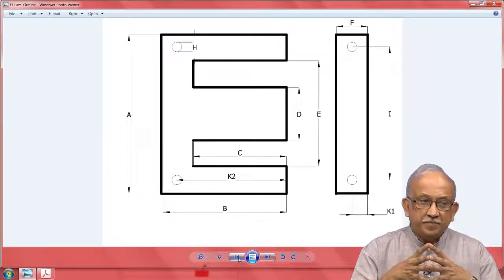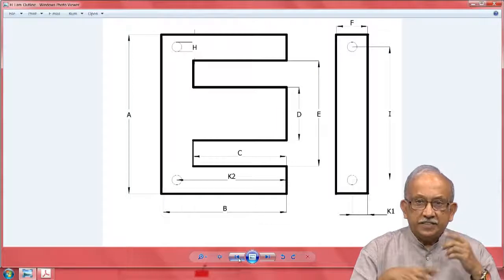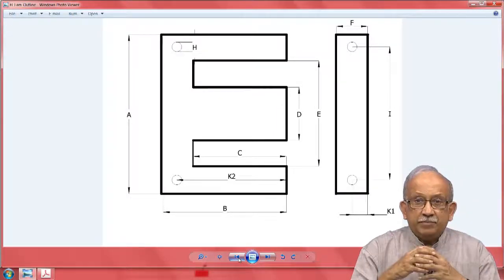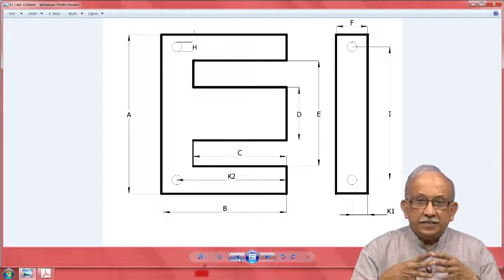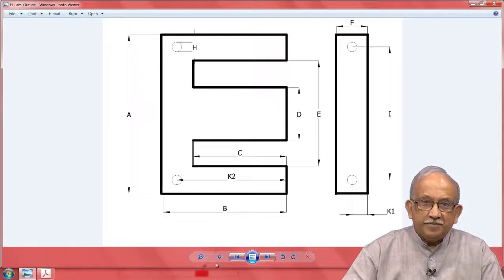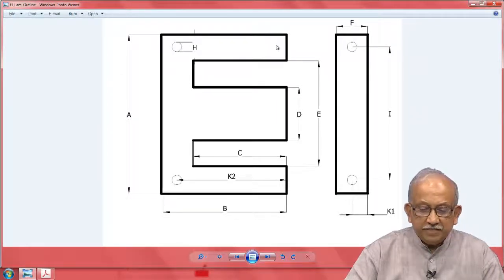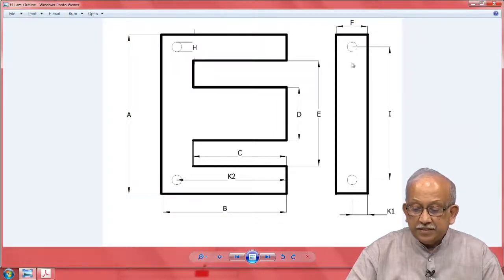Now, I will take you to a very familiar electronic object you are likely to see. This one is called an EI lamination, obviously because of the shape. Typically, the proportions have been so adjusted that if this is an E and the grains are in this direction, flowing in our drawing left to right, and imagine this small thing, the I portion of it, can be cut out of this portion, then these also will be in the same line.